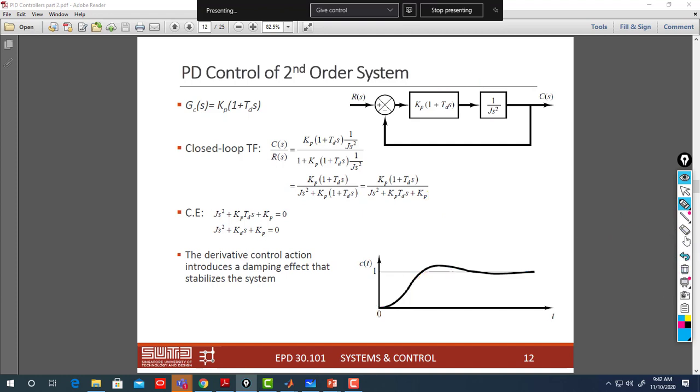Yes, doctor. And by the way, I usually like to ask this in the exam, just to check understanding as a concept question. What's the effect of proportional derivative? Where are the open loop poles? How will the closed loop poles be changed? Depending on the values of Kp and Kd, how will this affect the dynamic response?